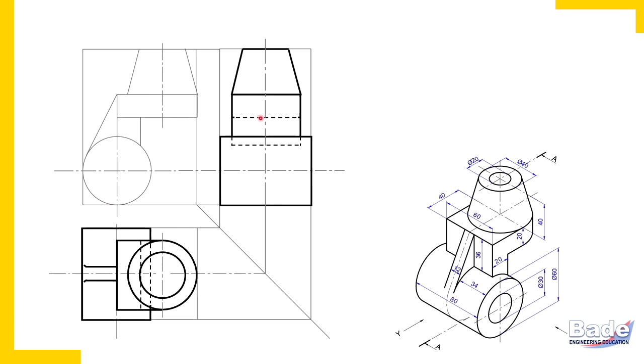Now let's draw this rib in the side view also. So height of the plate, so highest point of that rib, that is this corner, and lowest point on the rib, that is nothing but where it is tangent to the cylinder. From these 2 points you should draw projectors. From lowest point on the rib to highest point on the rib, that is the height of the rib. Height is vertical, so that height you should transfer in the side view, and the rib 12 millimeter thickness you can transfer from top view to side view. So this vertical 12 millimeter dimension will become horizontal in the side view. So you may measure it independently. So this is how we have completed the rectangular strip in the side view.